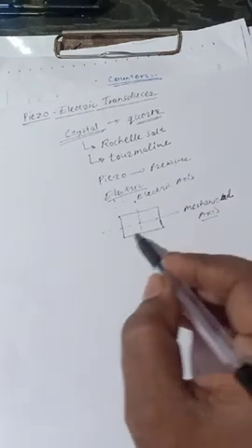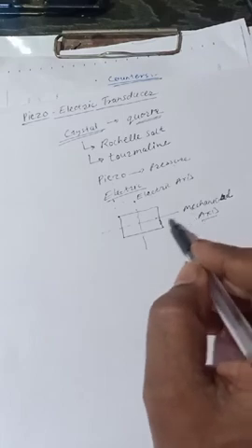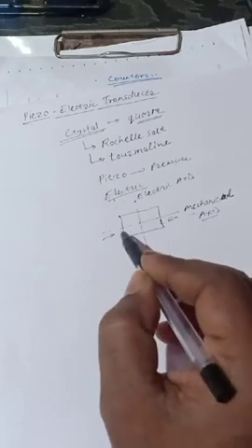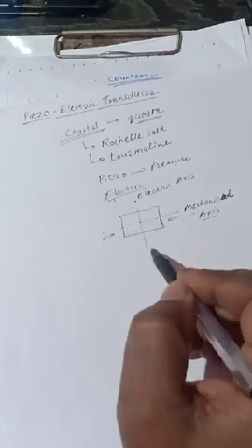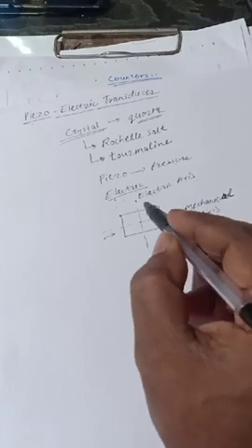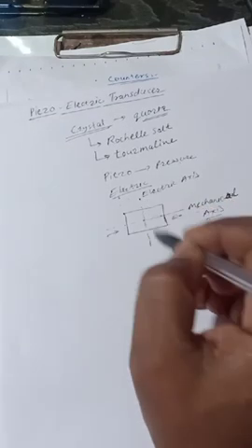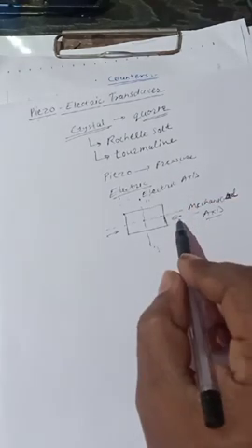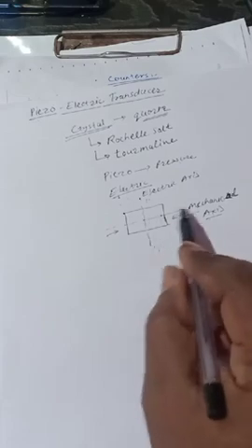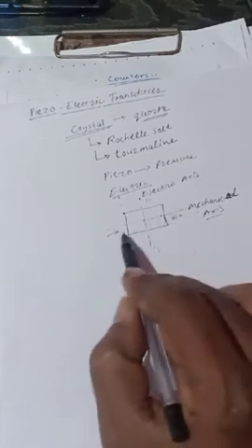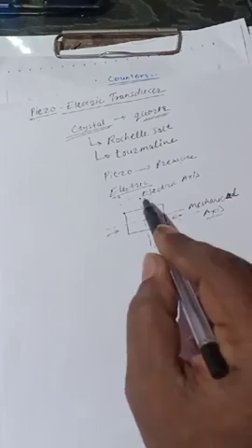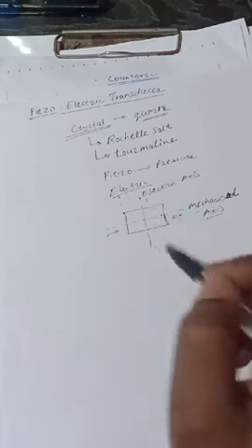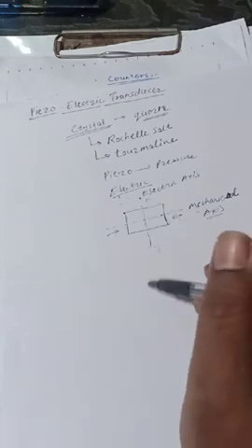If we provide a mechanical pressure on this axis from these two sides, then it produces a variable electric voltage on the other two sides. If we apply a variable pressure on this axis, it generates a variable voltage on these two plates.